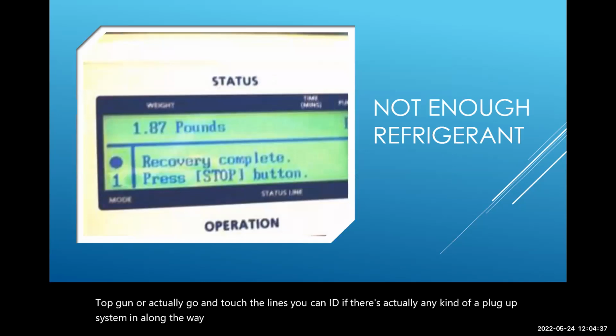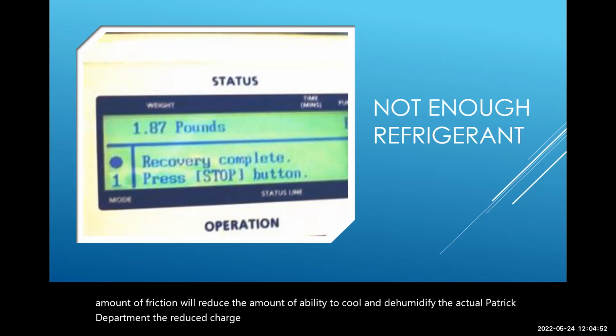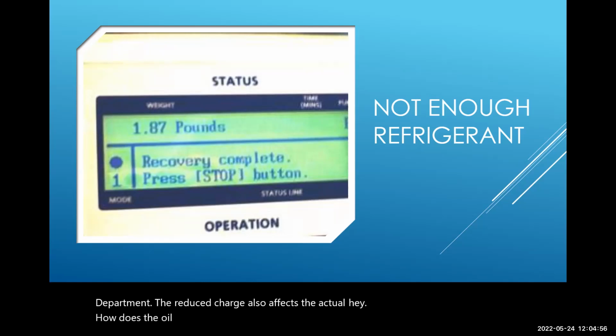So not enough refrigerant could be a problem. Any loss in the amount of refrigerant will reduce the ability to cool and dehumidify the compartment. The reduced charge also affects how the oil gets transported. It gets transported through the refrigerant, so we need to be able to circulate it around.